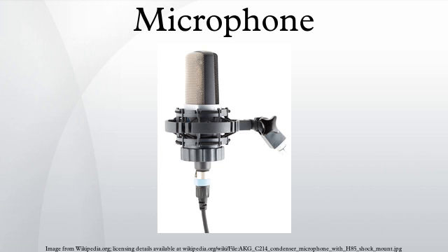MEMS microphone. The MEMS microphone is also called a microphone chip or silicon microphone. The pressure-sensitive diaphragm is etched directly into a silicon chip by MEMS techniques, and is usually accompanied with an integrated preamplifier. Most MEMS microphones are variants of the condenser microphone design.